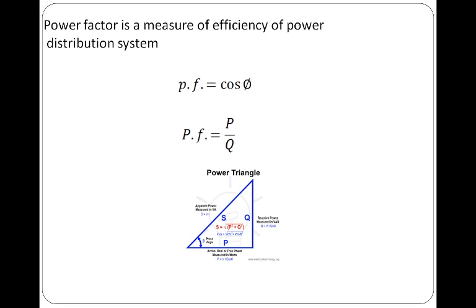The result is that capacitive and inductive circuit elements tend to cancel out each other. Where the waveforms are purely sinusoidal, the power factor is the cosine of the phase angle, as we are seeing here, the displacement between the current and the load.